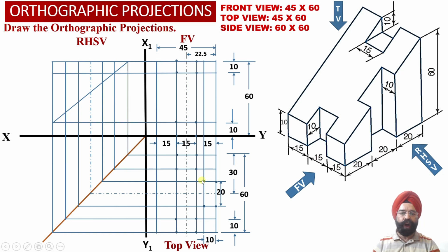So from one of the edges of the true shape of this rectangular slot, which is closer to the rear face of the solid, once we draw a horizontal projector line and transfer it into the right hand side view orthographic projections, we observe that this is the point of intersection between this inclined surface and this particular portion, which corresponds to this rear edge available with us in the top view projections over here.